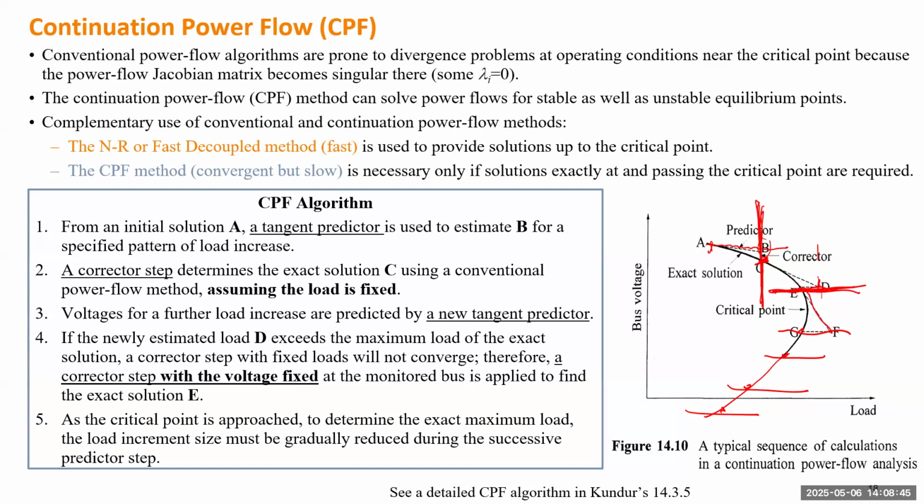So this method can give you the complete PV curve, but it doesn't guarantee the PV curve under the critical point to be correct. You only guarantee any PV curve above this point to be correct, right? Because you do have operating conditions there. But when you operate beyond this critical point, even though the software can give you that lower part, that may not be correct because you have to assume the load model to be this horizontal line, which has the voltage constant no matter what power. So that doesn't exist in the real world.